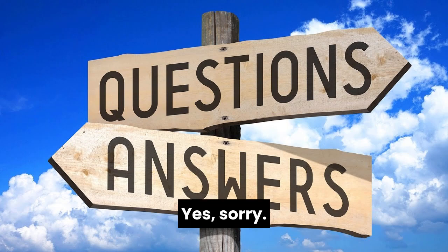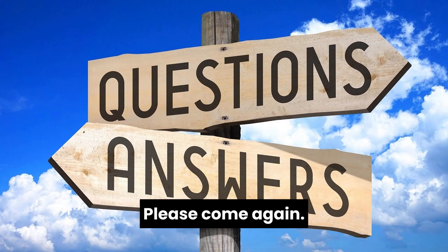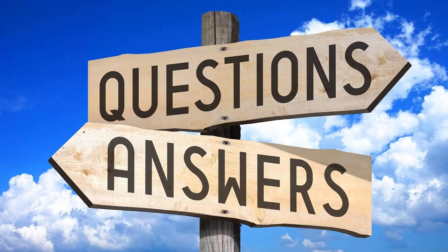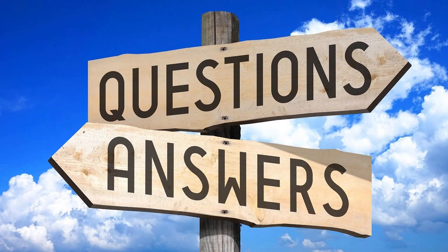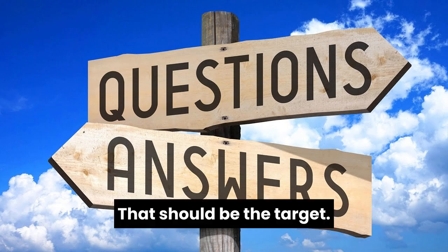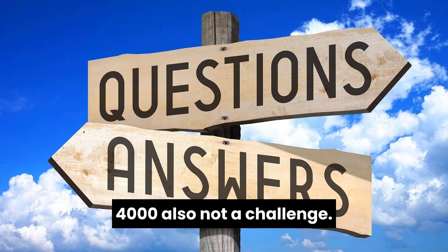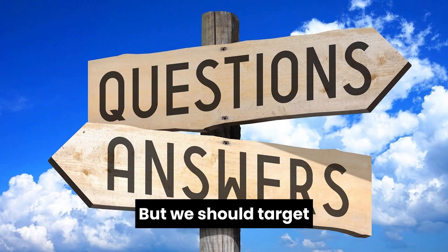In this case, we can maintain much MLSS. We should target at least 5,000 anytime. That should be the target. Even if it goes down a little bit, to 4,000 also, it's not a challenge, but we should target 5,000.